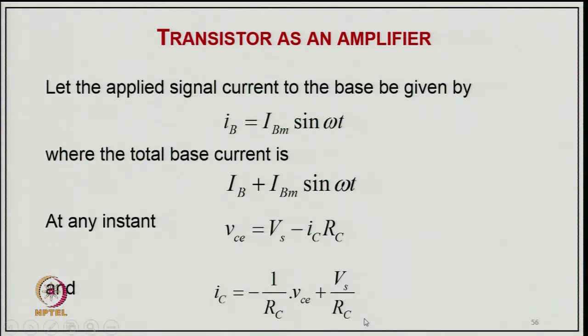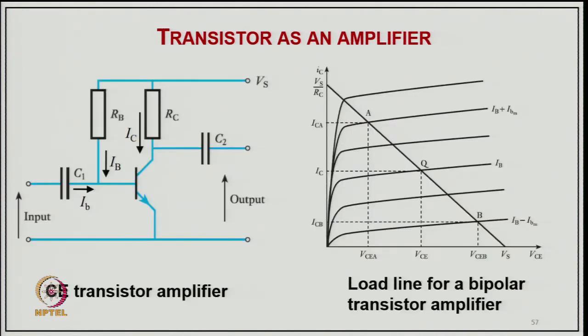Here also you are providing a kind of DC bias, and you can see the same circuit here. You have a bias at the base which gives you a DC component, and on this comes an AC component. So the transistor always has the bias in the unidirectional mode as far as operation is concerned, so that it works as an amplifier, and here also you get an amplified voltage, but this capacitor blocks the DC voltage.